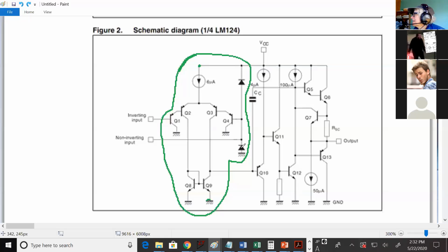Is the line side going to the lower voltage? No. So why are they there? How do they protect? Against current going the other way? Okay. So if the input voltage rises above VCC or below ground, it'll shunt the current to ground or VCC instead of back powering things?